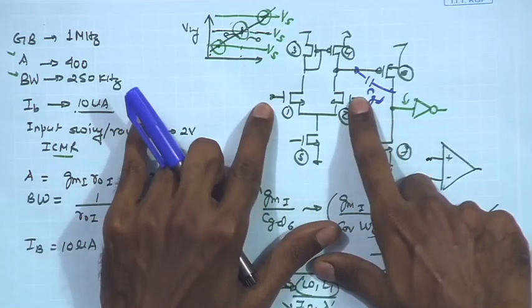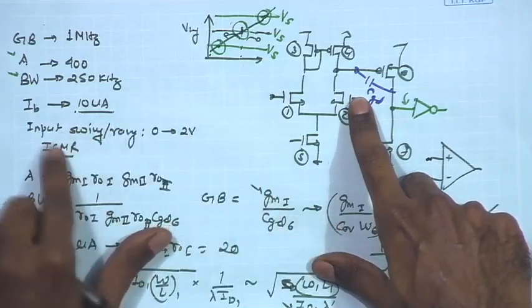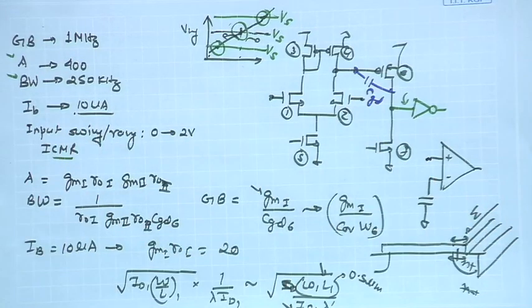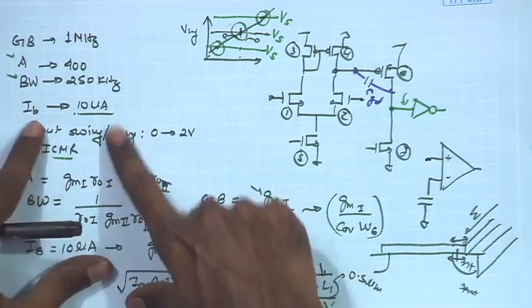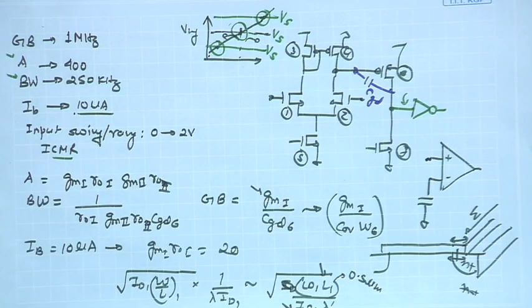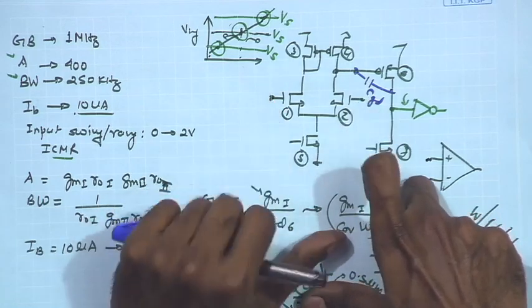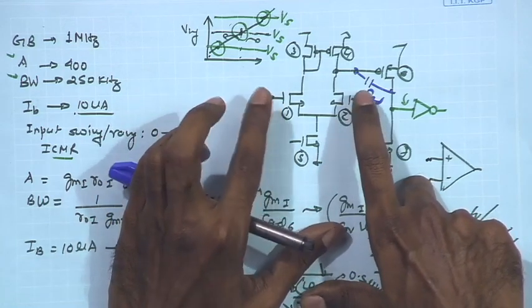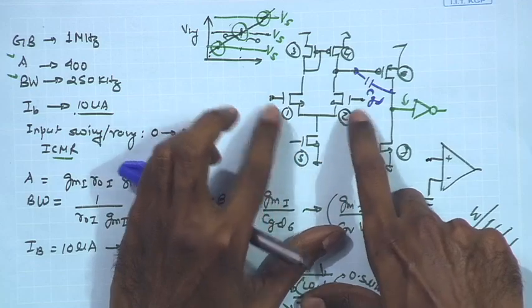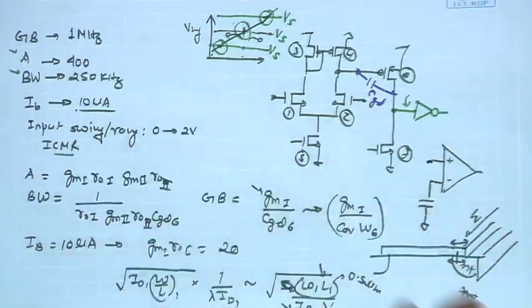So, this is regarding the sizing with respect to gain, and now gain and bandwidth while reducing the power consumption. Now, the other constraint that we mentioned in the very beginning is ICMR, where the input common mode range must be full swing, close to full swing. There, if you look at the criteria, the input device size is going to determine the ICMR on the lower side. Remember, what is the minimum input common mode voltage that you can apply at the input? If I look at the ICMR requirement, which I said is going to be more critical than the other constraints of gain, bandwidth, and power.